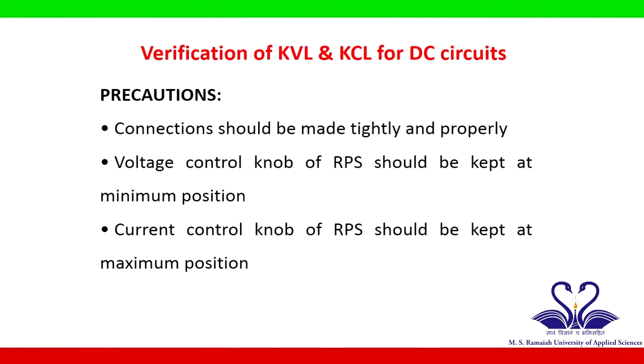Connections should be made tight and properly. Voltage control knob of regulated power supply should be kept at minimum position. Current control knob of regulated power supply should be kept at maximum position.